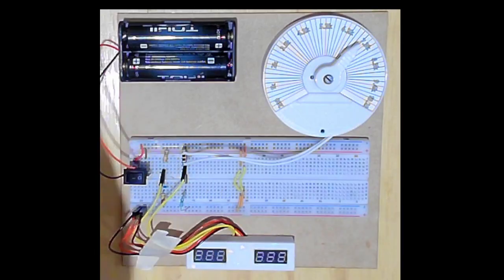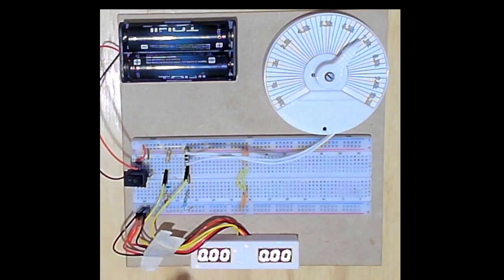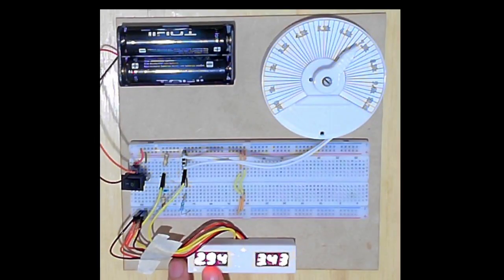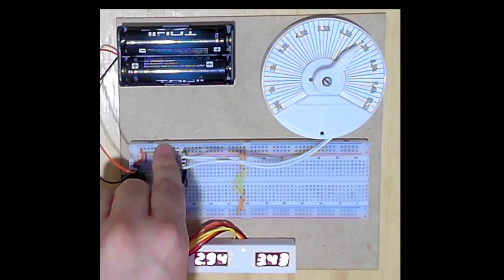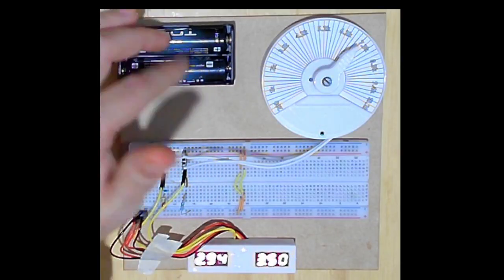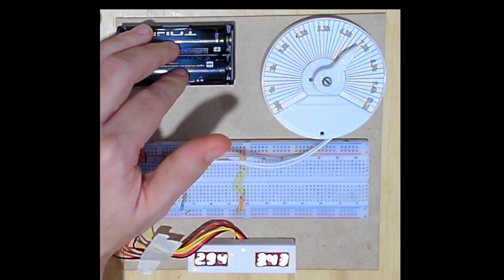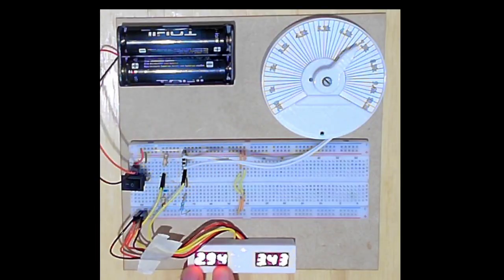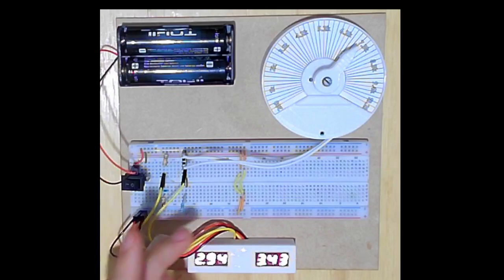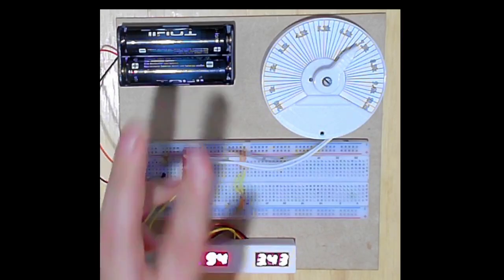So let me return to the camera. If I turn this on, I will get two voltage readings, right? Right here I have 2.9 volts. So this is for the voltage divider of the 10K resistors. So I am getting half of this, so right here I have about 5.8 volts, right? Then I have the middle here. And in this, I have the voltage divider that I am making with the unknown resistor. Right now, we know that it's the 10K resistor and the potentiometer.